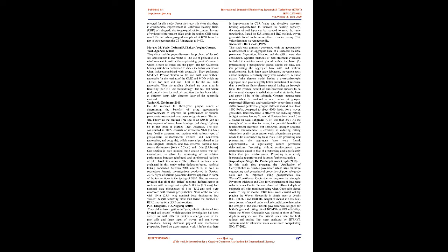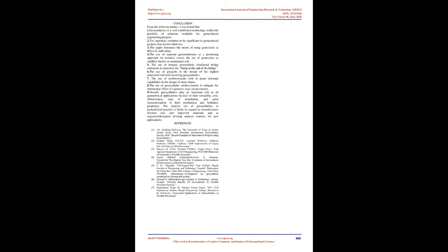Due to the increase in bearing capacity, the thickness of the soil layer can be reduced to serve the same function. Based on the U.S. Corps and IRC methods, woven geotextile was found to be more effective in increasing CBR value than non-woven geotextile.